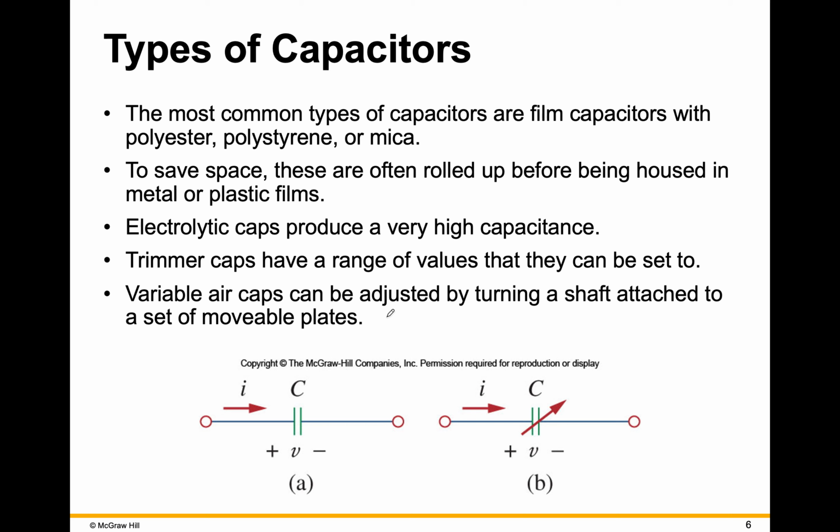So I talked a little bit about the capacitive microphone. That's how that works. It picks up basically the sound waves. The pressure from the sound waves will vibrate one of the capacitive plates, hence changing the capacitance and then giving you a variable voltage. Now, this Q equals CV formula is an important formula, because that's how you derive the formula for capacitance. That comes from physics. As I said, it comes from Gauss's law.